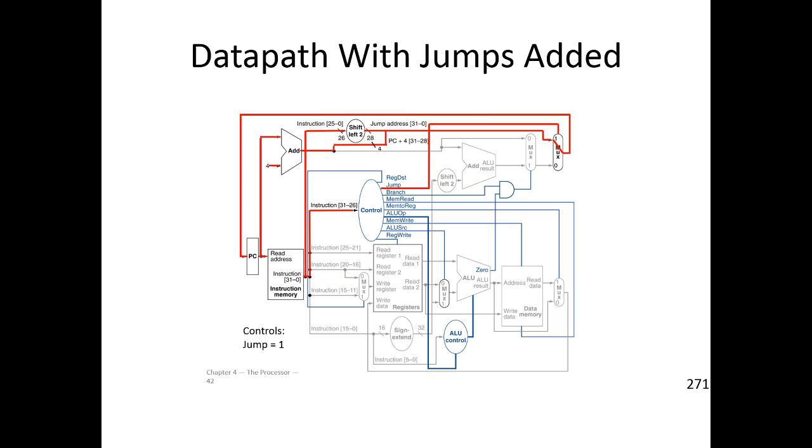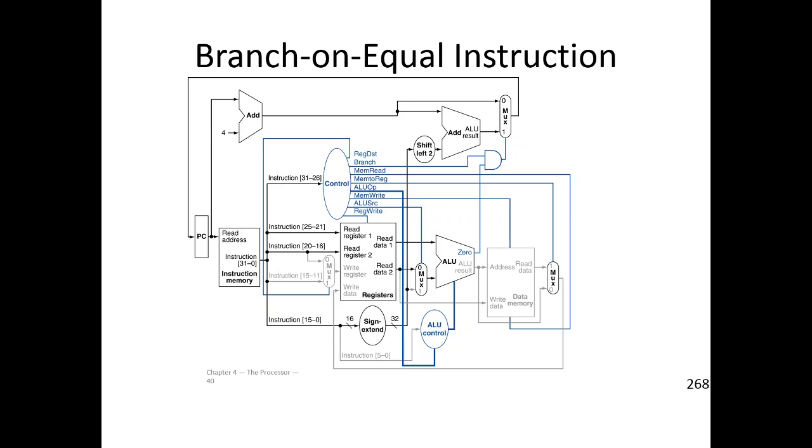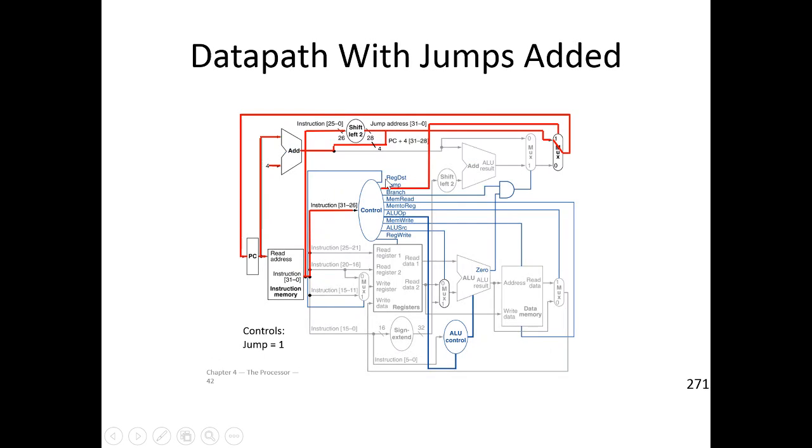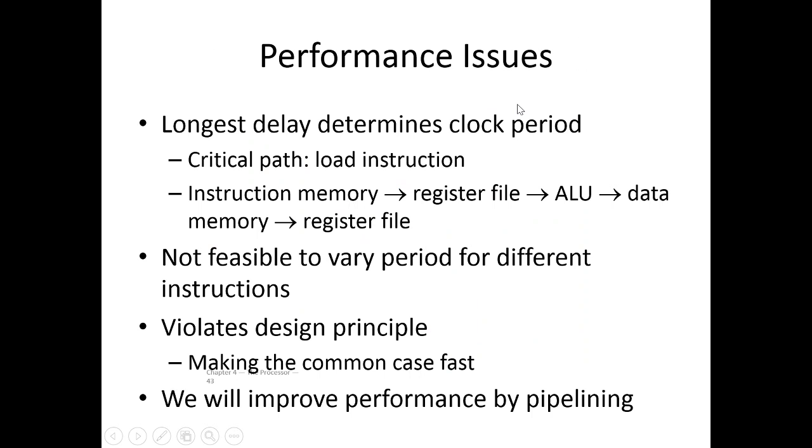Already talked about jump to implement the additional jump logic, right? You can see where it goes. It's not here, right? We have register destination, branch, memory. I kind of showed this earlier. Now we put the jump logic in there, okay, for where we need to add this additional mux, because this was for branch or PC. Now after that we also need to decide, is it a jump? Okay, so jump gets its own data path, kind of, in a manner of speaking.